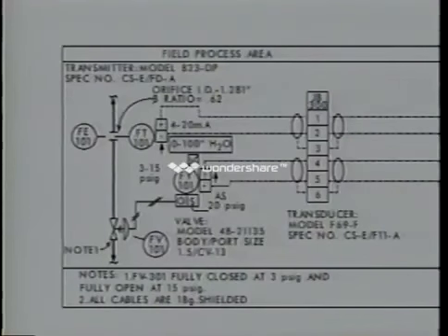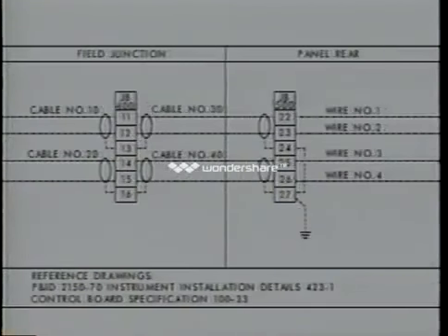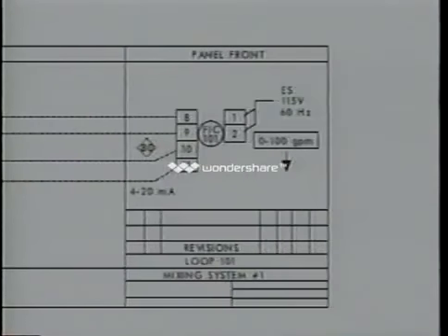Loop diagrams can be used in conjunction with P&IDs. Each loop diagram gives you a more detailed view of a loop in a process system. The loop diagram shows you the pneumatic or electric signal path. It gives you a better understanding of how the loop operates. A loop diagram has a logical method to help you read and interpret information. ISA Standard 5.4 discusses the preparation and use of diagrams for instrument loops.